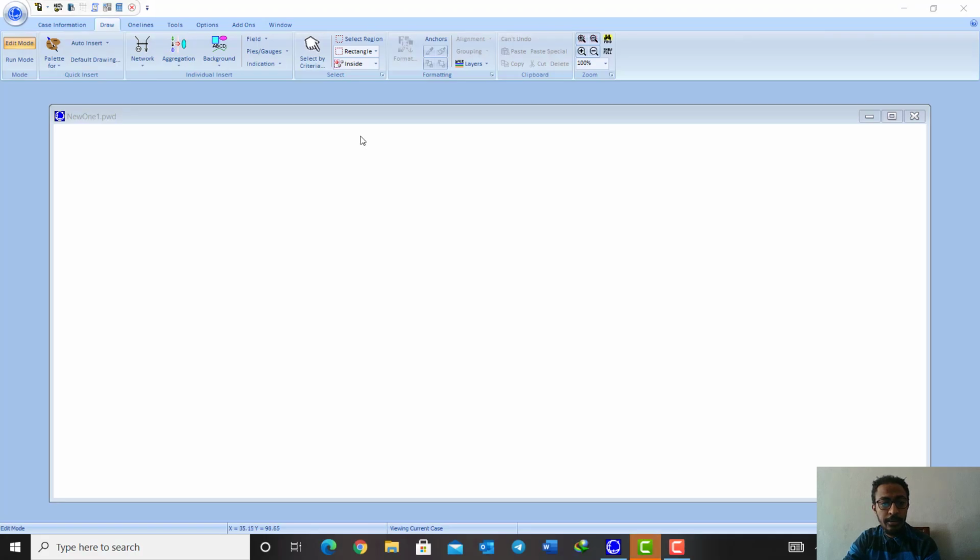Hello friends, today we are going to see the IEEE 3-bus system for load flow analysis or power flow studies of the 3-bus system. In this case, we'll have the bus, the generator and the load, and we can solve it by using the GS or NR method using the PowerWorld simulator software. So we can calculate the total megawatt losses and the total MVAR losses, according to the transmission line losses and also the transmission line megawatt and megavar output.